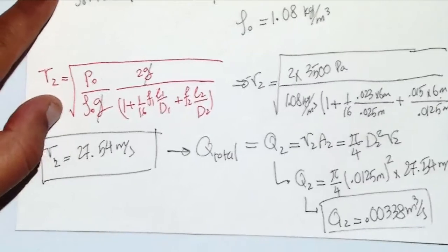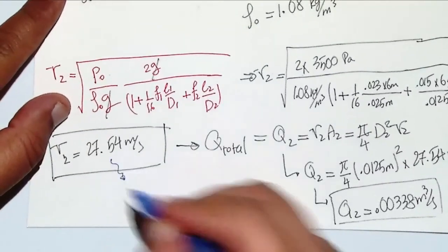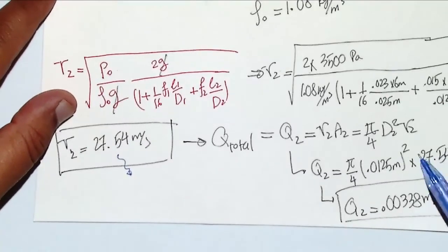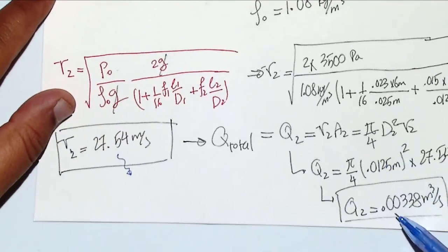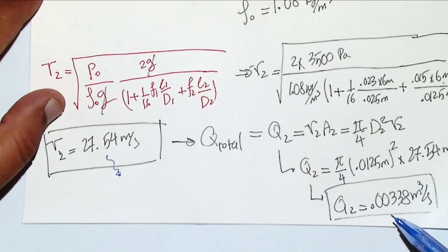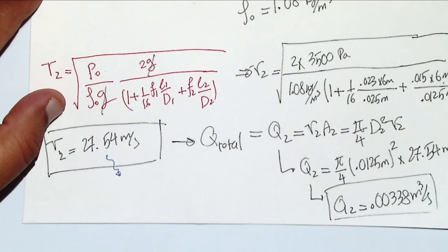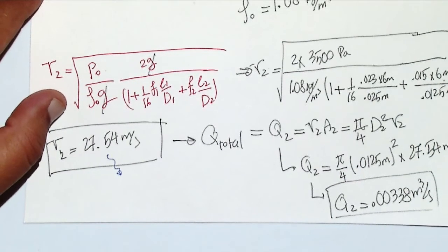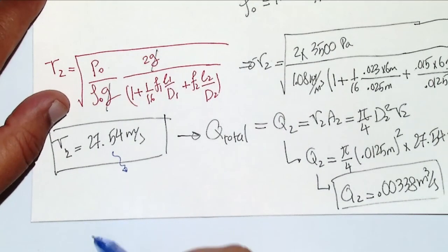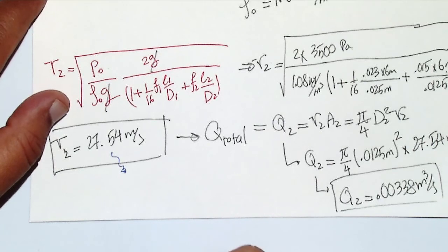But let's check what the Reynolds number is here, because you know that the friction factor for laminar flow is 64 over Reynolds, right? So you have an equation for that, but in this question the friction factors are given as two constant numbers. So let's check whether the flow is turbulent, since the question decided to give us the friction factor.